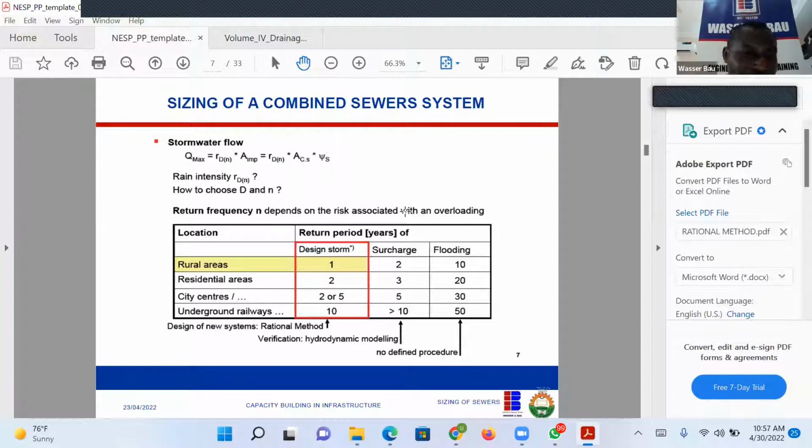But for today, we're using 0.37 because this is a rural area. That area might be rural today, but the way Abuja is expanding, in the next 20 years that place will become a semi-urban area, and then that design will still work. The idea is for your design to work as long as possible, to accommodate every possible externality, every possible change in land use based on human activity. So don't design something that after 5 years the whole thing will collapse.